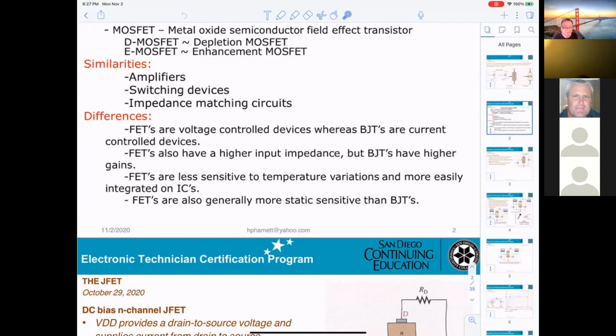Inside the factory, you got to wear a special suit, right? Right. Whenever you get a job, that is the first thing they train you, how to handle the IC. Bipolar, you can hold it, no big deal. But the FET you have to be careful.